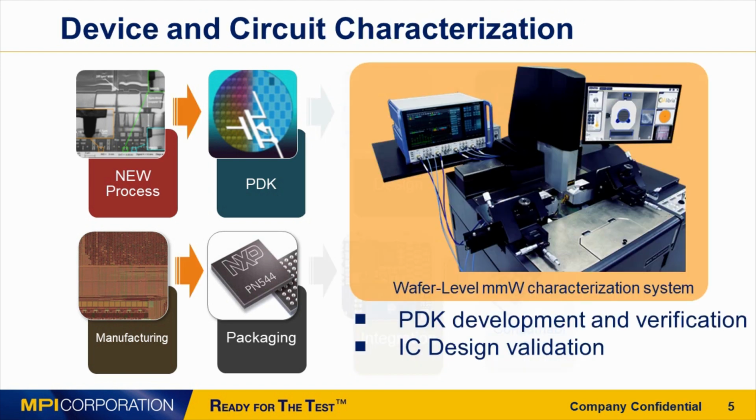The wafer-level device characterization is a crucial step in the PDK development of a new process. It is extremely important that device characteristics are measured at the highest possible level of accuracy and that the extracted device model parameters are verified for the entire frequency range of the device operation. Only by processing trustable and consistent device data can process development engineers be confident when offering PDK libraries to their customers, the circuit designers. And only by operating with trustable device models does it become possible to develop the product that will meet the product specification from the first silicon run.